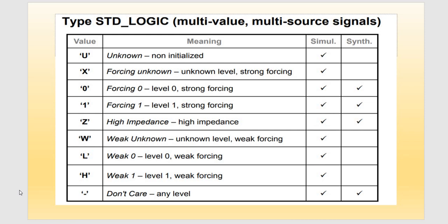One might think of designating bit positions that may safely be ignored during synthesis. So from that point of view, don't care is used. For simulation purposes, the opposite is desirable. That is a value which indicates that something went wrong and needs to be inspected, and that's why it is undefined. In the beginning, several incompatible multi-valued logic systems were defined by different software companies. In order to solve the resulting problem, a standardized 9-value logic system was defined.